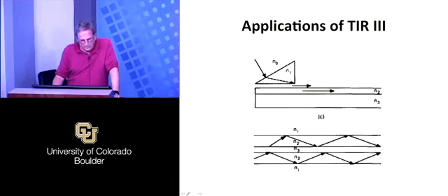That end won't look like that, I guarantee you. You spin the polymer on and this stuff won't go to the end. You'll try to cleave it and you'll shatter this part down here and you'll melt this part over here. You never get a good end face. And that's true of many different materials, many different processes. You can't cleave through both materials the same way.